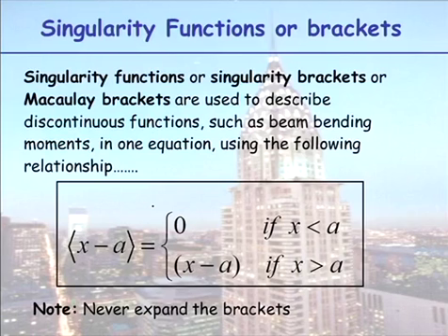Singularity functions or singularity brackets and Macaulay brackets are used to describe discontinuous functions, such as beam bending moments, in one equation. Using this fact, when we have an x minus something term, we put it in pointy brackets. And that's telling us we're using singularity brackets.